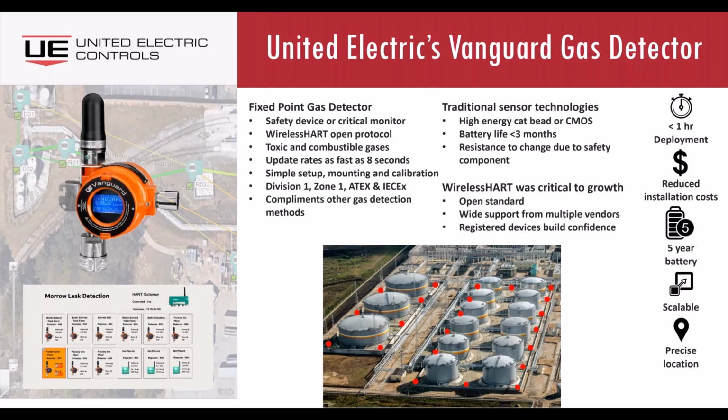And then gas detection is, put it where you can, and then hopefully get a lot more density of the measurement. What wireless is really doing is enabling that, giving you a scalable, cost-effective way to get a lot more points of data, so that hopefully you can detect that gas plume long before it becomes a dangerous size that can actually cause real damage, and then address that issue before it ignites.